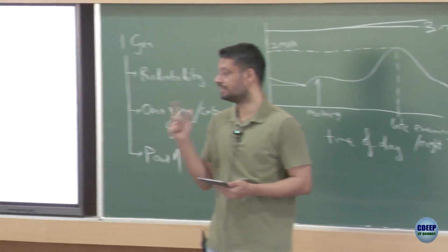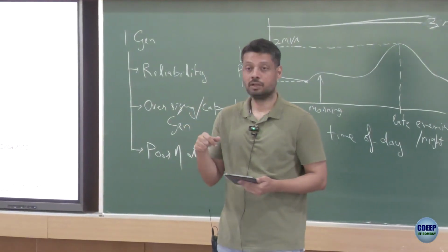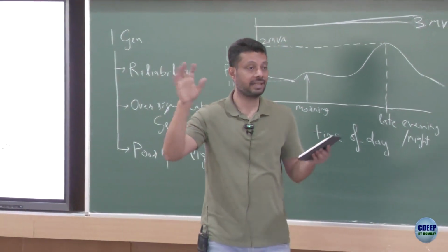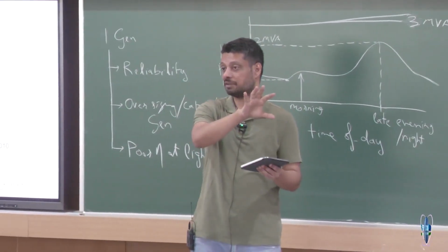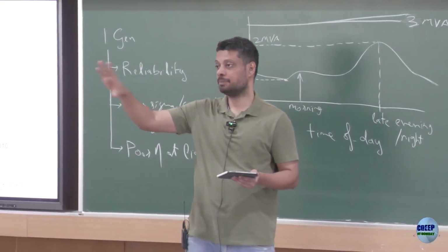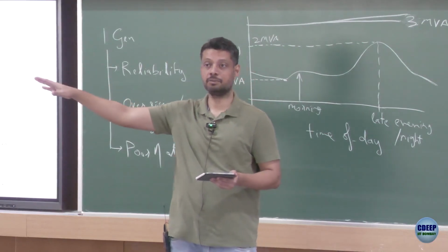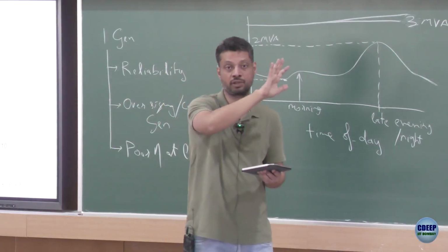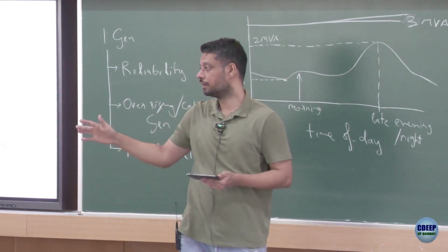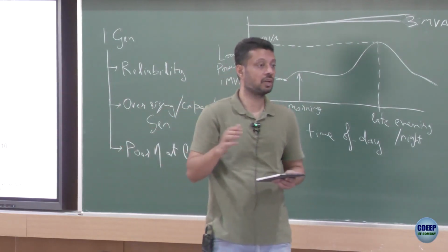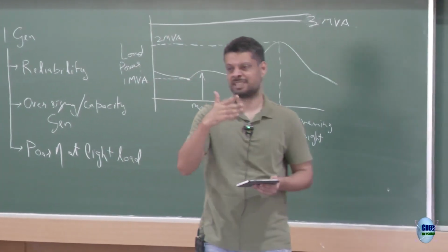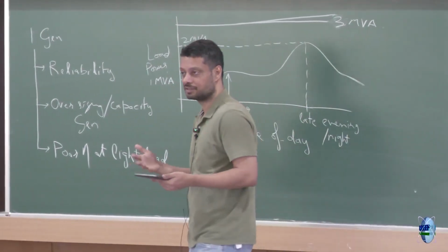We talked about HVDC in the beginning of this course. You can have 2 grids, connect them with a rectifier, pass on the power as HVDC, and then have an inverter. There you can still make sure the power flows from one grid to another. But that is asynchronous. We call it asynchronous because the frequencies on both sides need not be synchronized.